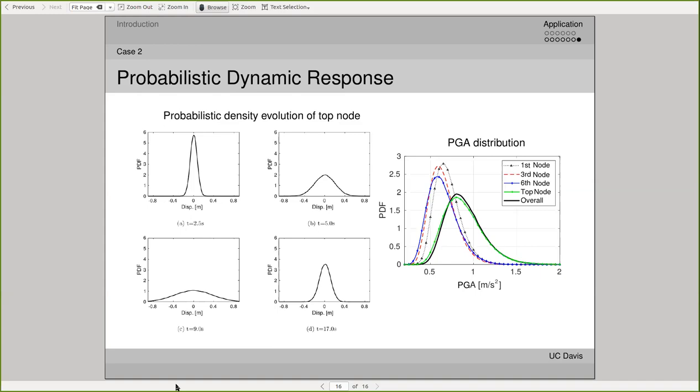What you can also do is integrate that, get CDFs, get fragilities, and this is all by taking essentially complete uncertain information about the excitation function. In this case, some motion at the bottom. Next time we'll talk about that some more, because with this method you don't really need to pick intensity measures, because you have complete information.